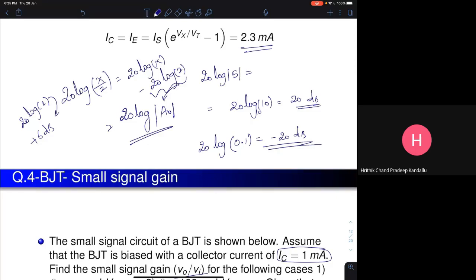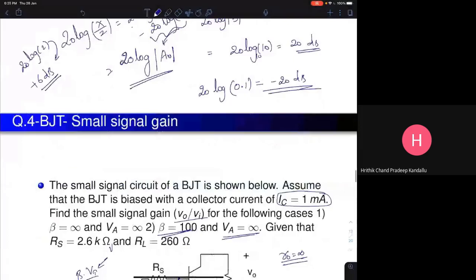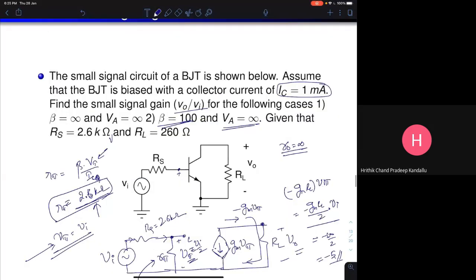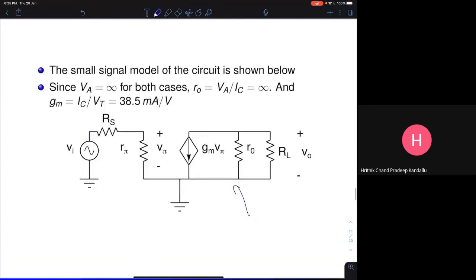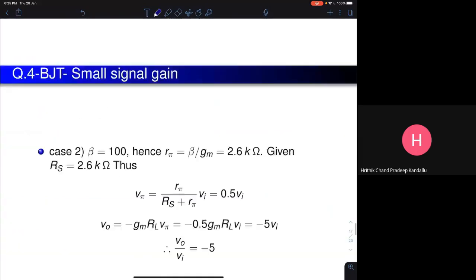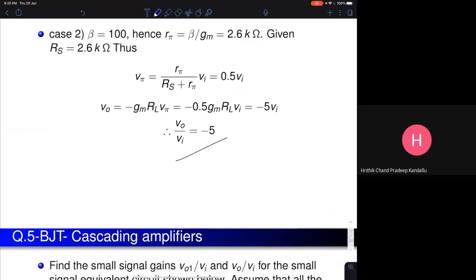That's a rule of thumb. They will teach you in greater depth in control systems. Everywhere you will encounter the 6 dB word. I'm just telling you now. So your gain will reduce by 6 decibels. That's one rule of thumb that you can remember. Okay. So that's it. I've solved this second question as well. The gain will become minus 5. So 10 is in the first case. Second case it will be minus 5.